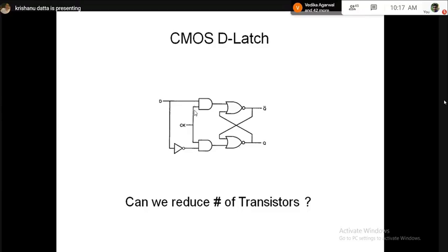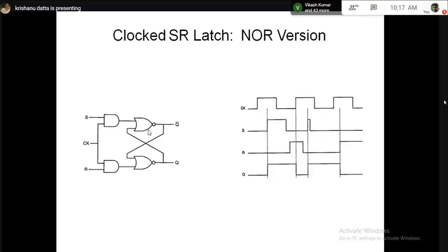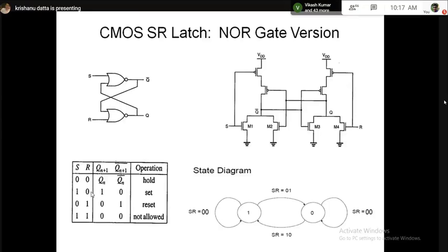This means now for this particular circuit, the relationship between S and R is such that it is either S1 R0 or S0 R1. So now if you look back, when S1 R0, always Q is 1. When S0 R1, always Q is 0.